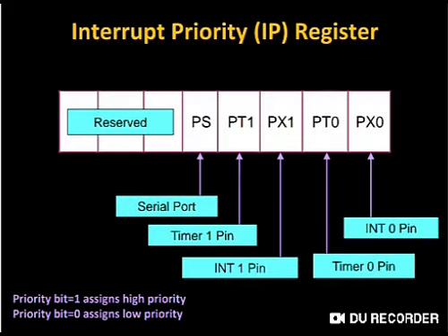So in 8051 interrupts, the important topics to be understood are the concept of interrupts, the concept of the interrupt service routine, the interrupt vector table addresses of the 8051 microcontroller, the way to enable or disable the interrupts using the IE register, and finally setting the priority of all the interrupts using the IP register.